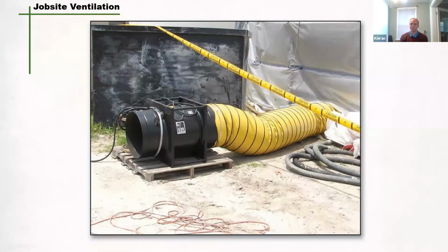So for some tasks, there's a low risk. If you have a building with bare studs, it's a good chance that the convection of the wind will ventilate for you. That's not to say that if you're working with an extremely volatile substance that you're fine. You have to check the SDS, check the recommended usages, and find out if it's hazardous, even if there is good ventilation. In that situation, you may be required to go further and wear personal protective equipment.